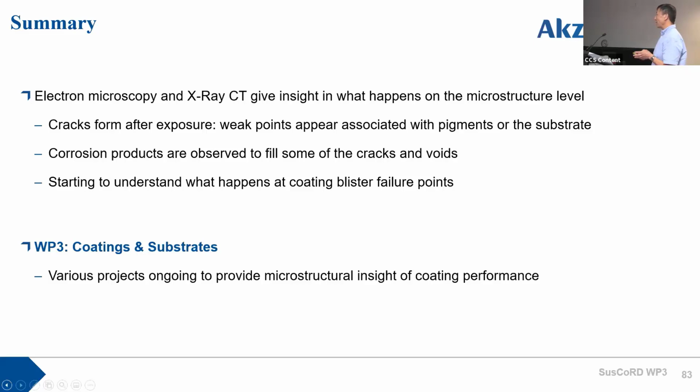And now we have a couple of new projects which will look at new microstructure features which can possibly relate to the performance. For example, as we just showed, the network of porosity is important for transport of effective inhibitor species. And from a previous project Reza worked on, we found that the particle volume concentration is important. But what about particle size distribution? If you have the same particle volume concentration but different particle size distribution, would that give you different performance? This is the focus of one of our new PhD projects.